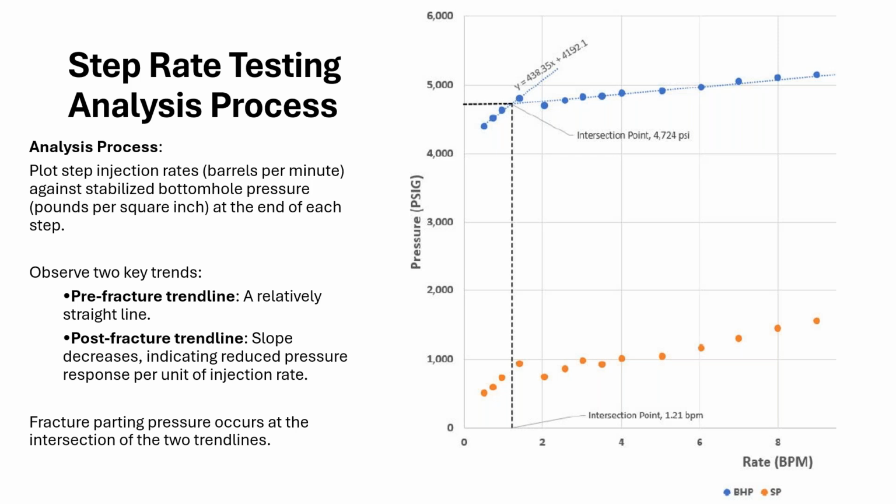But again, that may not necessarily be reflective of what a parting pressure would be if you see a trend line change or a change in slope, as again, those are the early times where you see large effects from your density changes, your temperature changes, and your viscosity changes downhole. So we would recommend at that point relying on your bottom hole pressure, shut-in pressure. You could plot that at your zero intersection point.